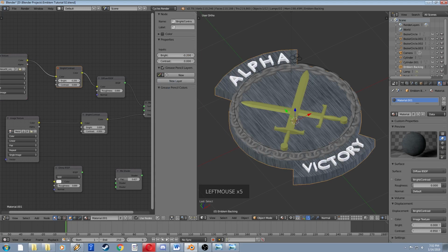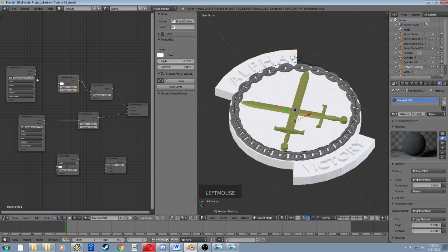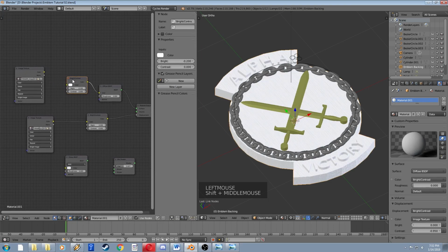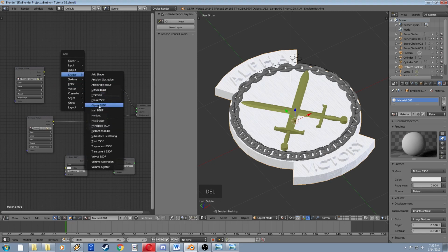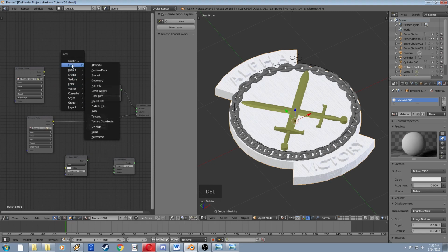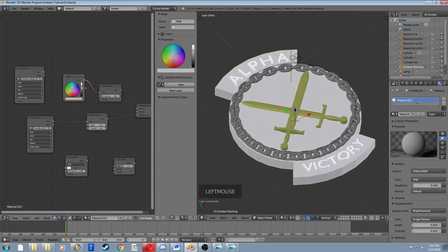Now we're ending up with a lot more blue than we want. In fact, I've kind of decided now that steel, the original steel texture we're using, is just blue by default, but I don't really like that. I kind of want it to just be perfectly gray. So instead, what we'll do is we'll just take it out of the chain. We'll add an input RGB node right here in its place.